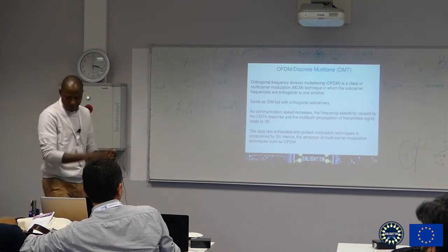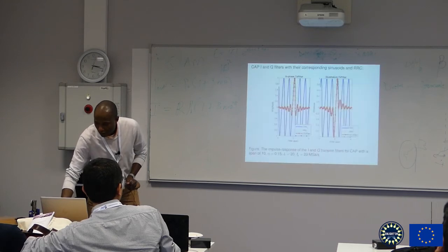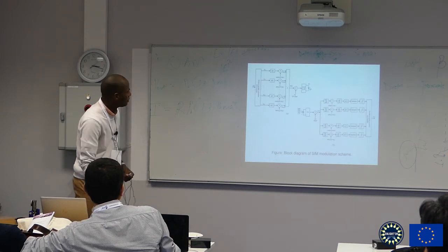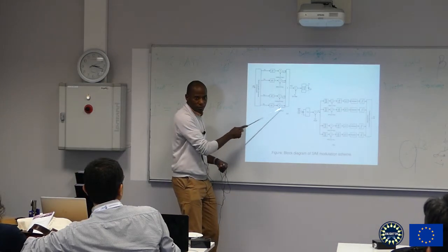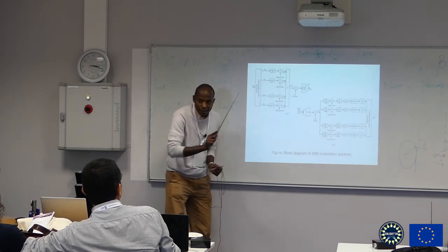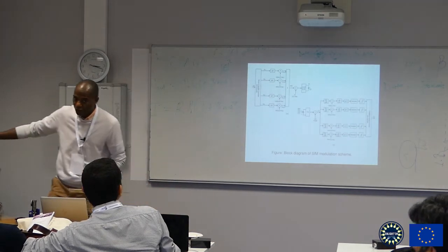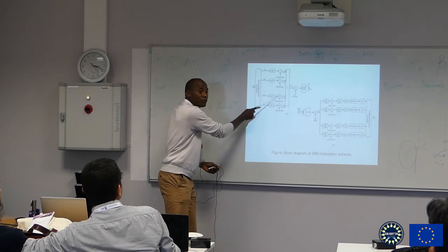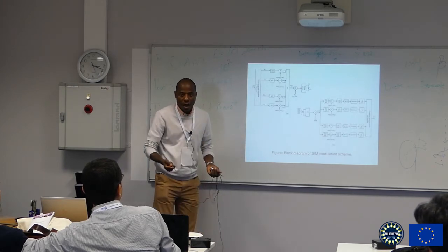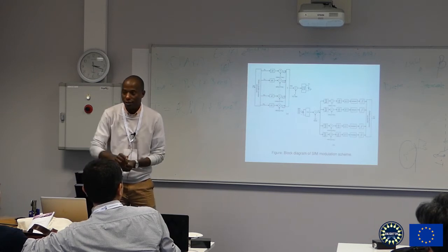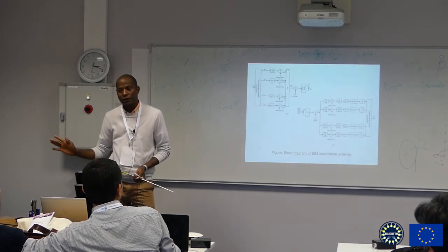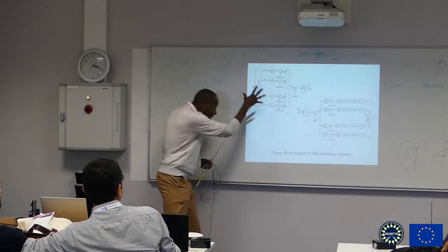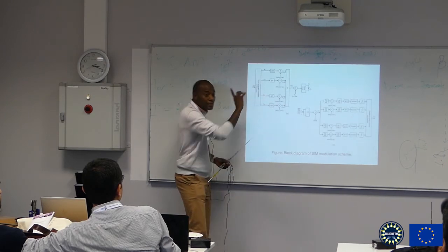Okay. Again, to talk about OFDM, have we heard about OFDM? Anybody? Okay, very good. So if we've heard about it, I'll come back to this diagram to explain. Here, I've said we can have multiple subcarriers, and I've not said anything about the relationship between the subcarrier frequencies, right? When it comes to OFDM, the only difference is these subcarrier frequencies have to be orthogonal. When I say orthogonal, I'm guessing we all know what I mean, right? That is, they don't give each other crosstalk. That's the only difference between them.